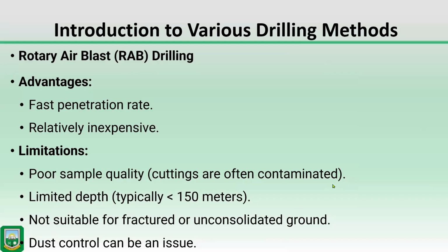Then the limitations. First is poor sample quality, because it is using compressed air to force the cuttings up to the surface. Those samples or cuttings cannot be used to represent the true nature of the ground where we obtain the sample.